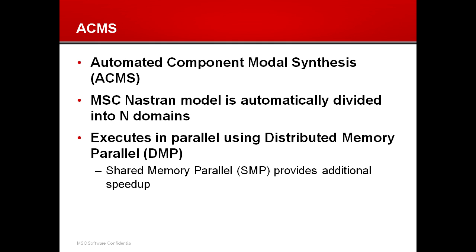Well, eigenvalue analysis is a critical part of MSC Nastran. It's the heart of NVH, noise, vibration, and harshness analysis. It's the backbone of acoustic simulation. And the procedure that's used in MSC Nastran is ACMS. ACMS stands for Automated Component Mode Synthesis.